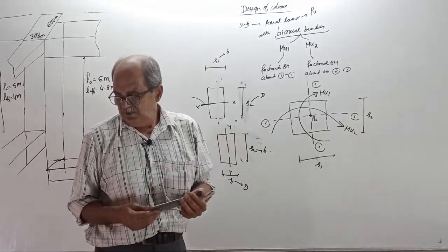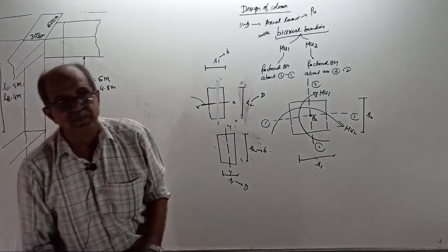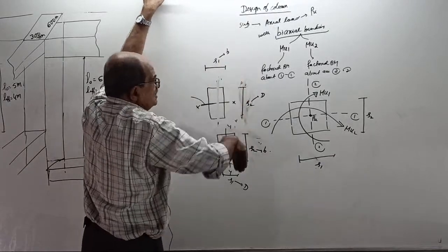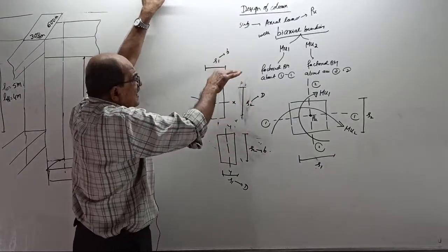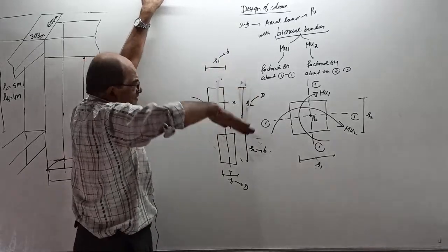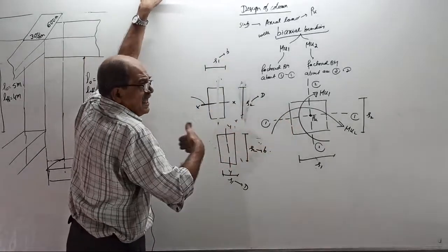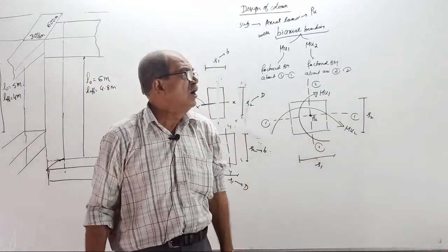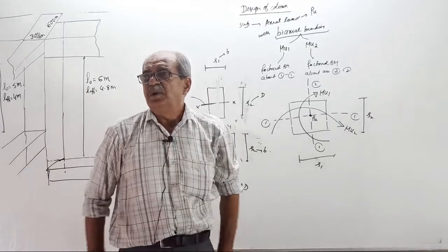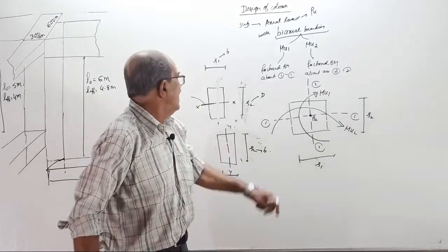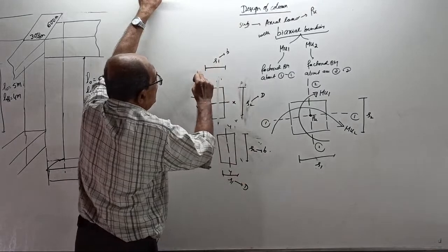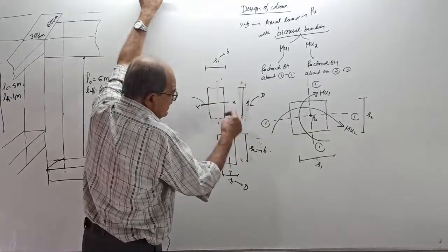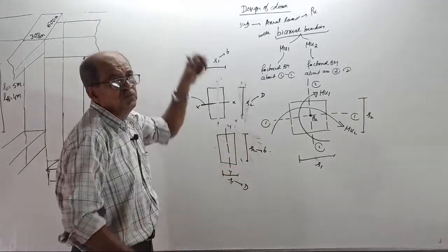See, this is first of all strength of materials. With respect to x axis, this is the depth. So it is difficult to bend like this. Actually, it is easy to bend like this. Therefore, where resistance is more, or where depth is more, remember, in strength of materials, I about this axis is S1 into S2 cube by 12. I about this axis is S2 into S1 cube by 12.